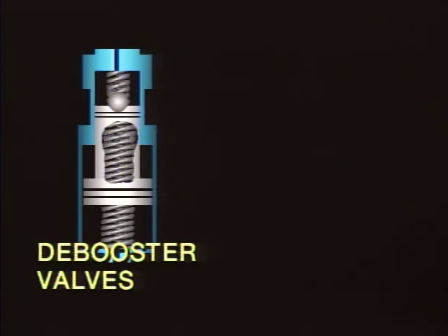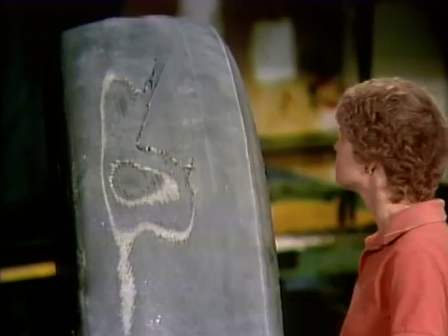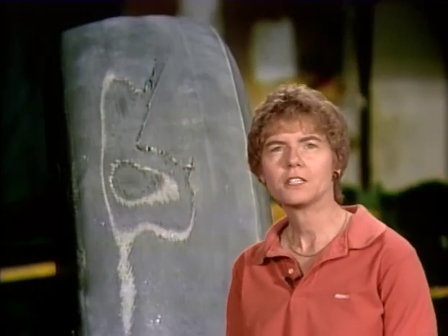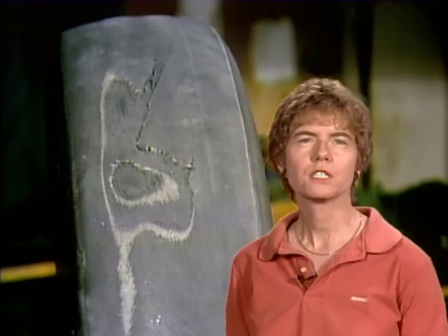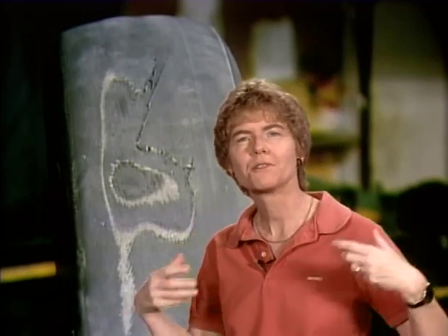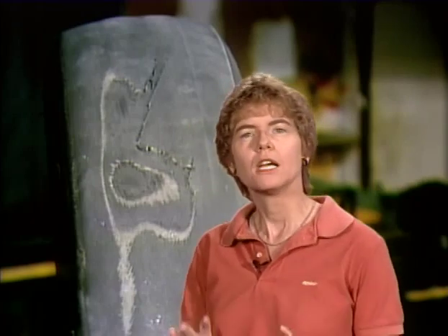Okay, let's talk about anti-skid. This tire, as you can see, has had a bit of a skidding problem. Anytime a wheel goes into a skid on an aircraft, effectively the aircraft can't brake anymore. The aircraft's braking value, as the FAA puts it, is greatly reduced if a wheel has gone into a skid.